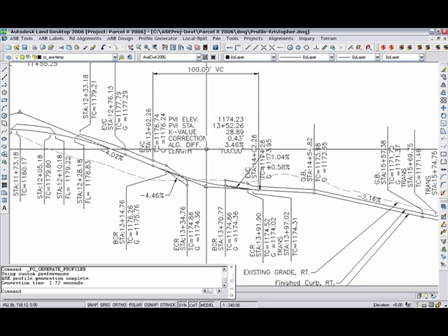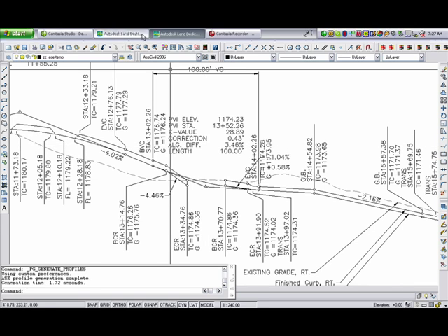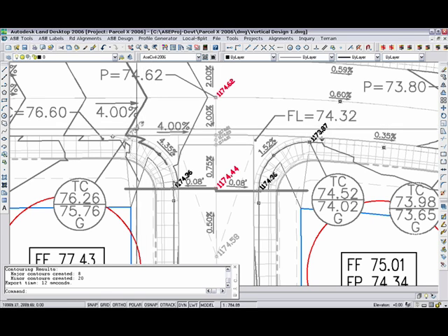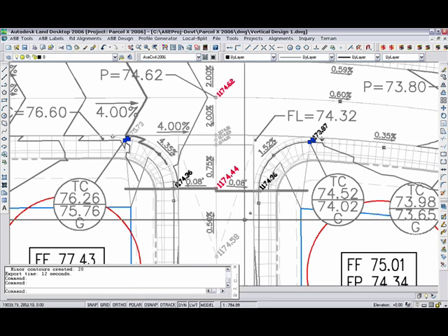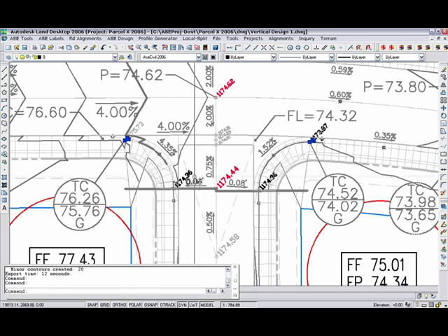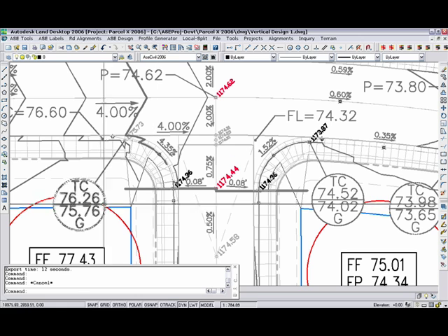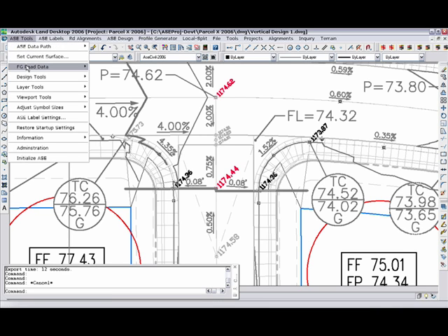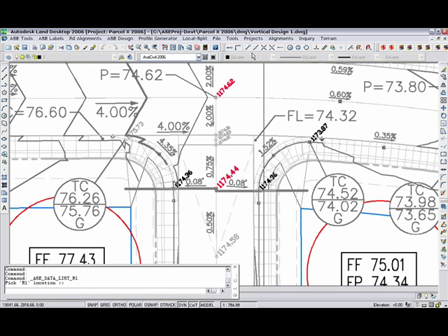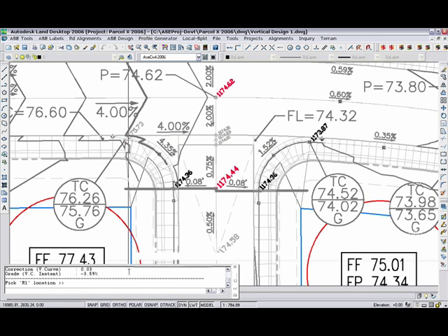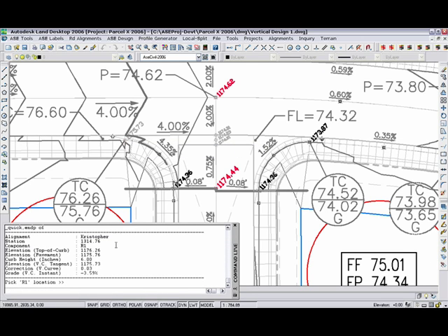Now, one thing that's important to note here is that in the design drawing, the design markers at the tangent points of the intersection will not update, and the reason is because a lot of times those may be linked to something else. So even though these design markers do not show the vertical curve elevation, everything else does. The road model, the paving labels, if you were to list the road data on the R1 component, where you've got a vertical curve going through an intersection, you will get the correct elevations, 7626, 7526.